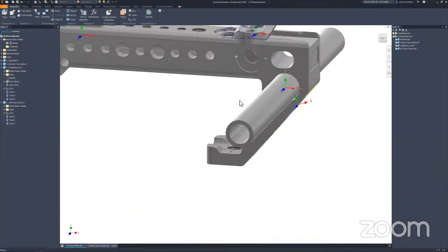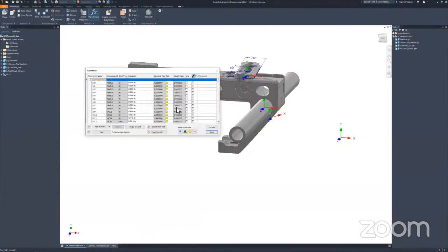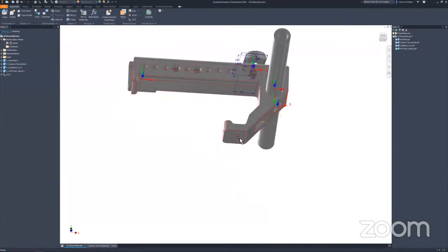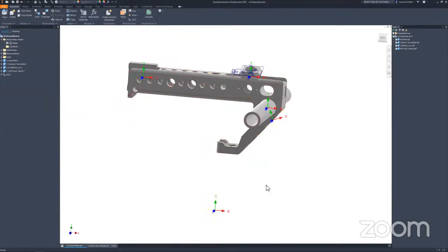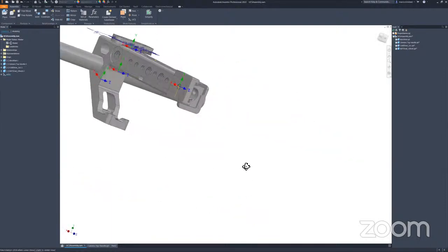But yeah, if you want to place one, like I mentioned at the beginning, if you place it out into space, it defaults to the origin. So go ahead and place that one. And then you're going to see that one actually shows up under parameters here, and place that at 0. I can place another one within the part. Let's say if I wanted one down here, or somewhere else centered in here, and then I can go ahead and constrain them together. That way, that new point that I placed will move over here. And then my whole part is set to the origin where I want it to be.